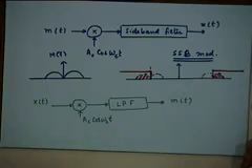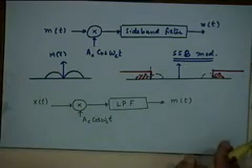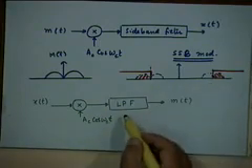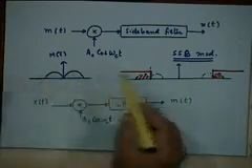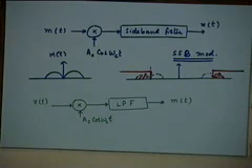Are you all with me? So the demodulator remains exactly the same as what we had for DSB-SC. Just apply the frequency translation theorem onto this spectrum, and you can see that your baseband spectrum comes back, along with a component around 2fc, which will of course go.